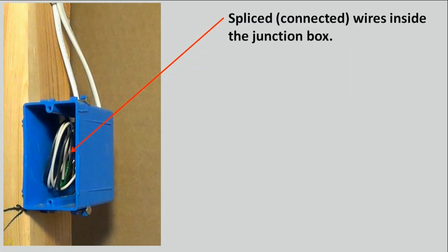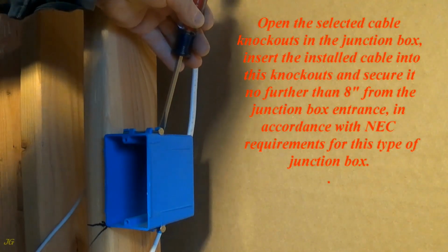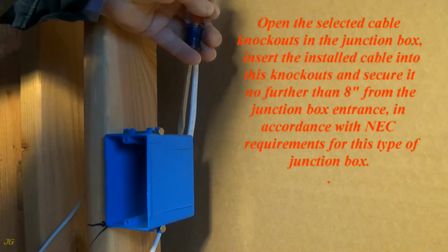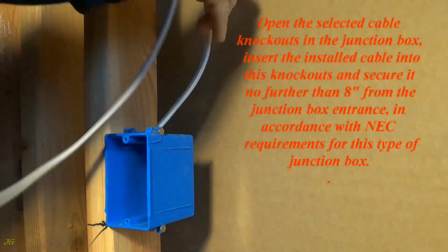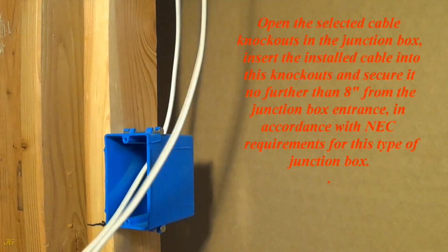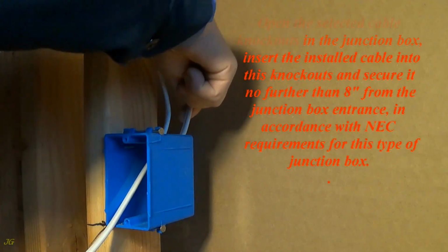Spliced, connected wires inside the junction box. Open the selected cable knockouts in the junction box. Insert the installed cable into these knockouts and secure it no further than 8 inches from the junction box entrance, in accordance with NEC requirements for this type of junction box.